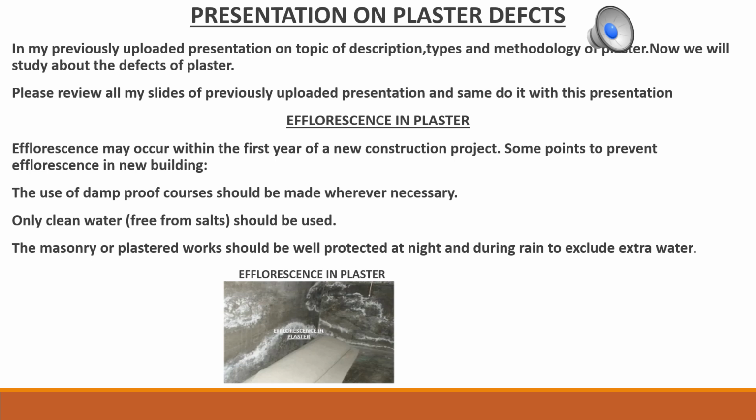In that case, we can do the damp proof course, DPC, if required on the plinth beams, as specified by the structural consultant. Efflorescence can be removed only by clean water, to remove the salts from the exposed surfaces.